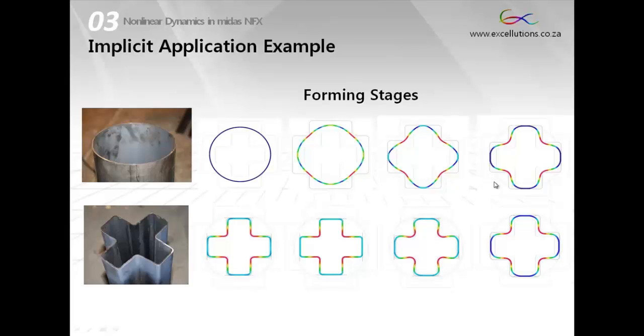We tested the concept of invoking 4 buckle points through a roller system. We continue to press on the mating surfaces until full buckle occurs, and the profile then finds the mandrel on the inside. Sufficient pressure was added, and on the final picture just before the cross-section photo, you can see that the surfaces were lifted a little bit, and we could see how much springback will occur.